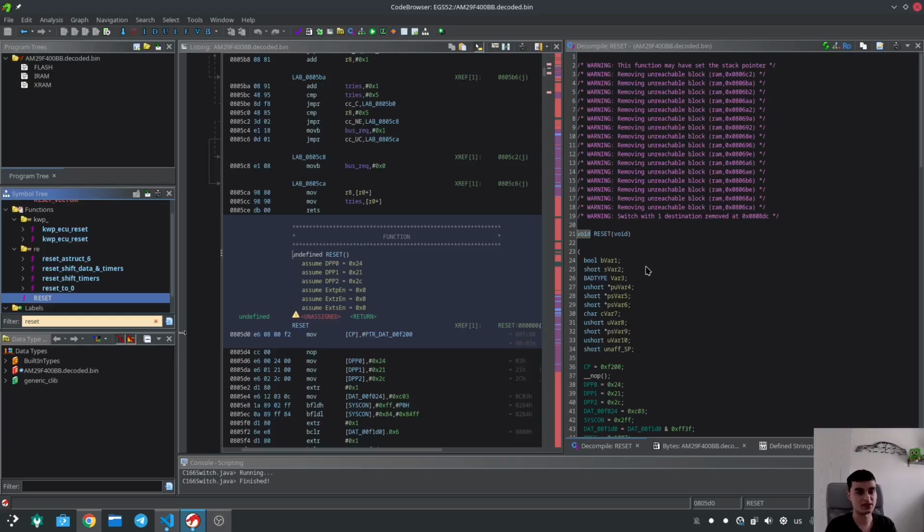So first of all, let's look at how EGS's software is structured. You see here in the middle, there's this red bar. This bar represents various parts of the flash. So here you've got the start of flash, and here you have the end of flash at the bottom. This purple stuff here represents functions and code which are in the bootloader region. So when the CPU turns on, it does a bunch of checks, and then we'll jump to main software. Main software here is this second bunch of purple and blue.